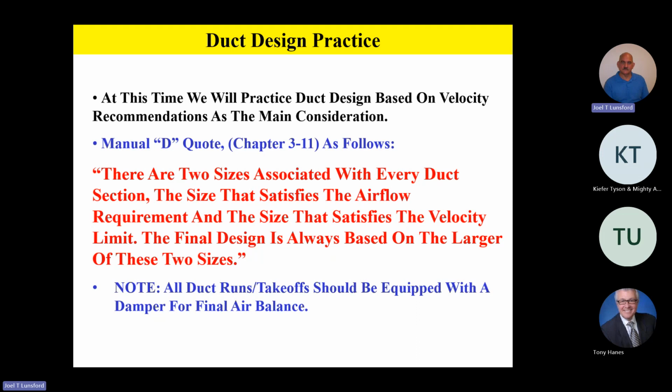And so what we're going to be doing today, we're going to be focusing in and studying the velocity method of duct design. Now, maybe you haven't used this method before. It's very, very simple. Basically, we're going to take our duct calculator. We're going to design around a target velocity. We'll then plug in the CFM off our duct calculator, and then at that point, we'll be able to see what size duct we need.